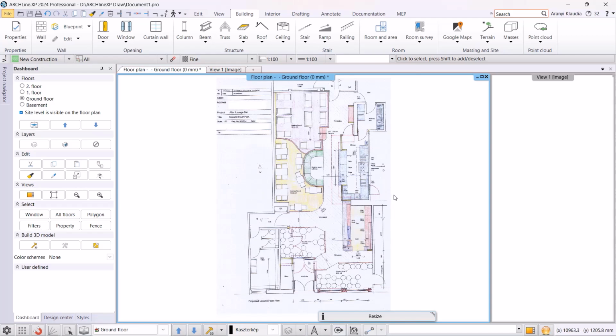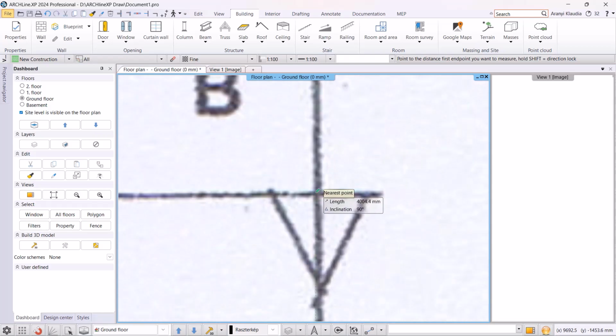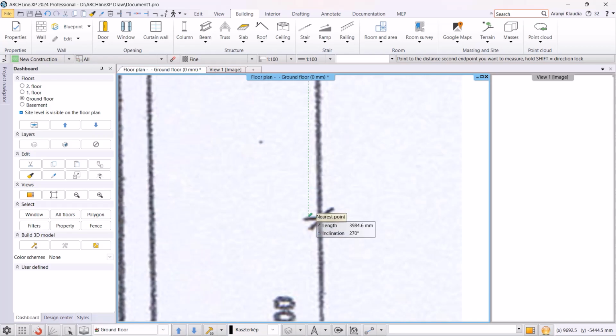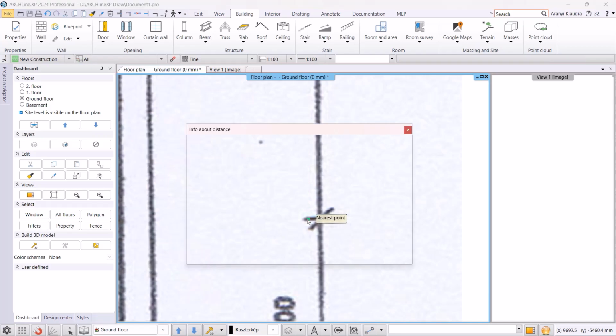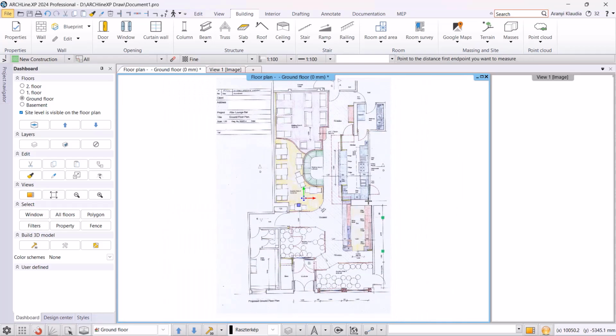I have to write in the actual size. I accept it, then check the accuracy of the calibration. This time selecting the Measure command from the quick toolbar. Let's see if the calibration was successful. It is also advisable to check a dimension in the horizontal direction.